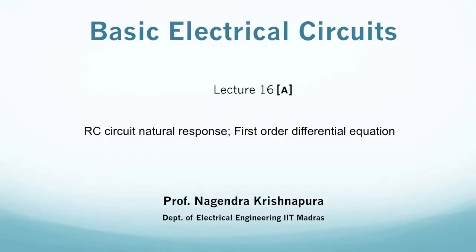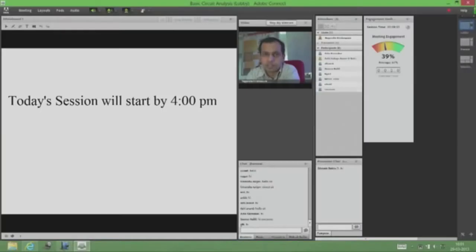In the previous lecture, we discussed in detail op-amp circuits. We looked at a couple of example op-amp circuits, and also I emphasized that op-amp has to be used in negative feedback, and I also mentioned how to find the signs of the op-amp in any circuit such that it is in negative feedback. Okay, an op-amp is basically a voltage controlled voltage source with a very large gain. Because the gain is very large and it's in negative feedback, it forces the input signal of the op-amp to be a very small value, which can be considered to be 0.